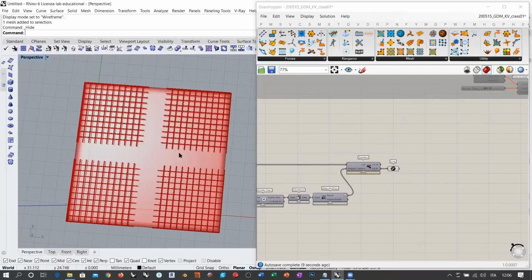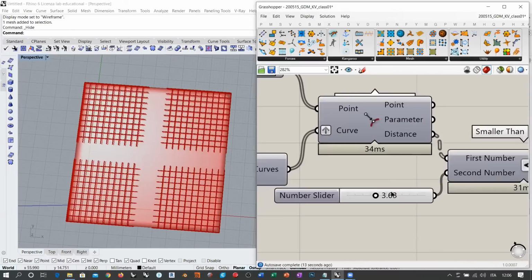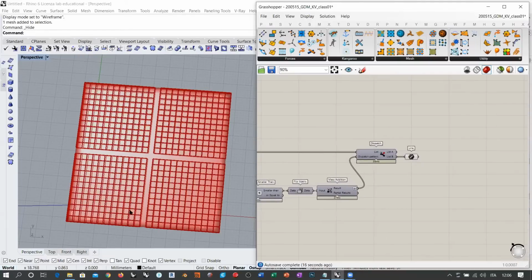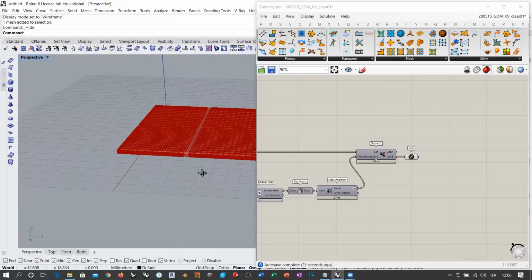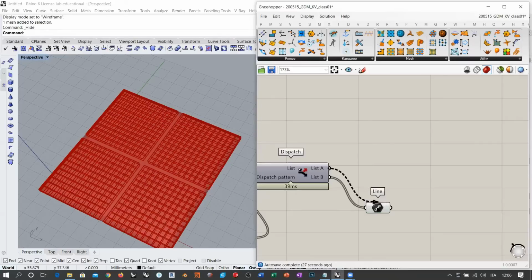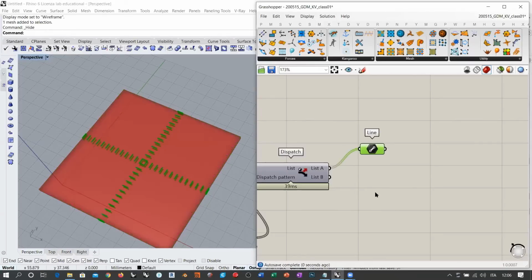And that's it, because from now on we can work with what we already know. Okay, so we can decide, for example, the tapering that we are applying, if it involves only the central edges, like for example like this, while all the rest of the edges, which are left free from the attractor, can work with the pressure that we want to apply. So for example, let's say that I want to apply some tapering only in the center lines, and I leave all the rest free, like this. So the center lines are these lines here, okay? So this is where the tapering is taking place. So I want these lines to be stiff.